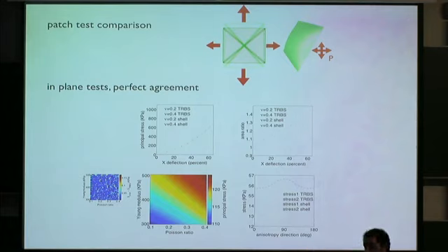But shells have thickness, and when they meet each other, if you bend a junction, which is the intersection between two shell elements, you have to deform them. Otherwise, you cannot. Which is not the case for the planar elements.